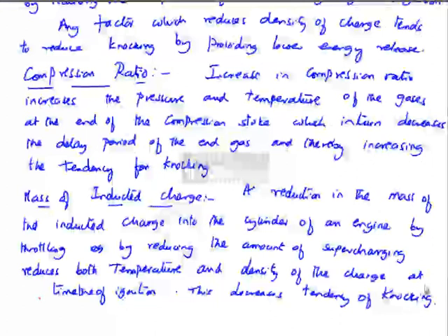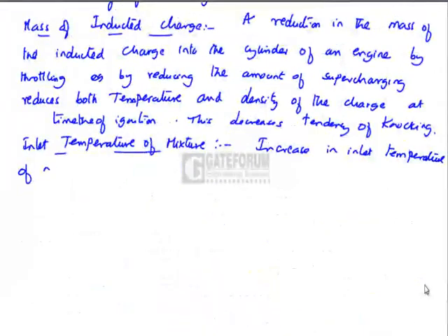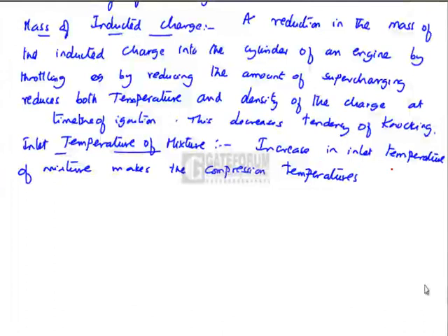Next parameter is inlet temperature of the mixture. An increase in the inlet temperature of the mixture makes the compression temperatures higher and thereby increases the tendency for knocking.